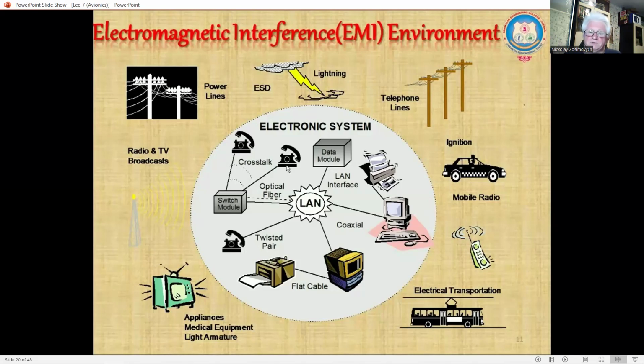This has been due to the susceptibility of the flight control system analog electronics to EMI because of inadequate electromagnetic screening. Current digital flight control systems are designed to a much higher electromagnetic compatibility, EMC, specification. That is the ability to withstand high levels of EMI, and they should be able to withstand such an environment.